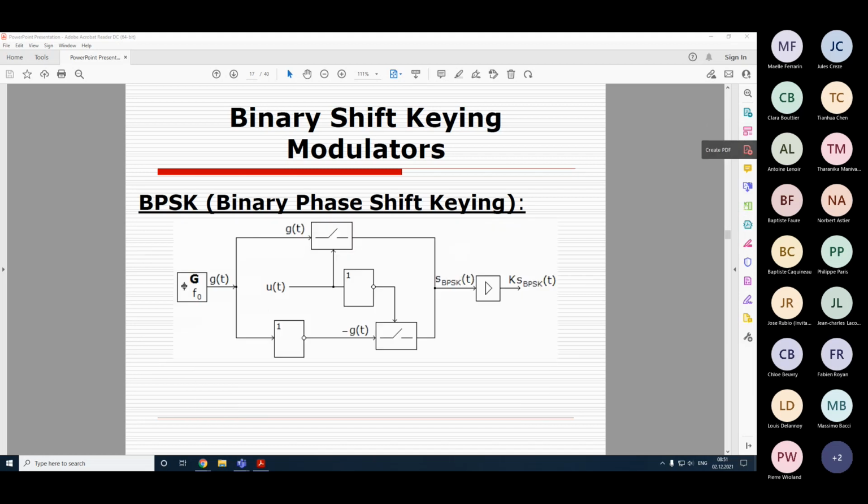Yes. So that's why we have a single generator, and similar to the frequency shift keying approach, we use two electronic switches, which accordingly are controlled with the same signal. Only thing is that the first switch is controlled with the direct signal, and the second switch is controlled with the inverted signal. Also, we need to invert the sine wave. So here we should have the sine wave, and here we should have the opposite phase sine wave. Yes, for that reason we also invert the sine wave.